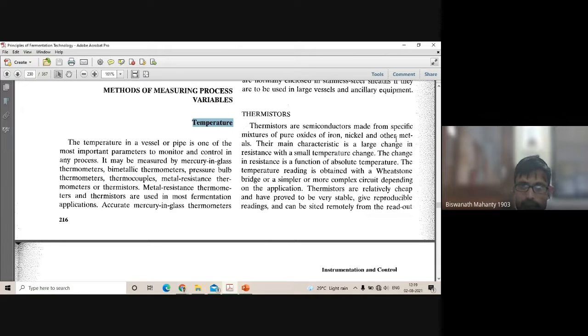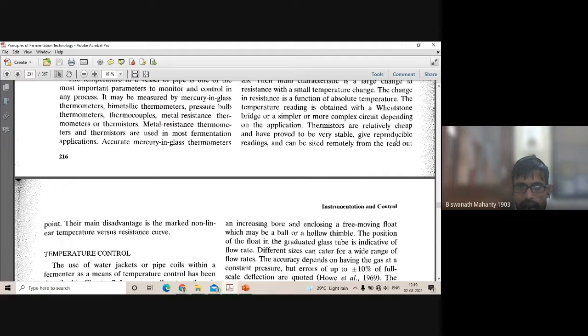A thermistor works on the same principle to measure how much temperature change is happening in this process. It is really cheap and it can make measurements, but sometimes when the resistance is increased to a high level, the temperature change and resistance are non-linear. So some problems can be associated with these kinds of thermistors when you use them in online temperature monitoring and control devices. So these are the things you need to understand when you are going for temperature measurement.